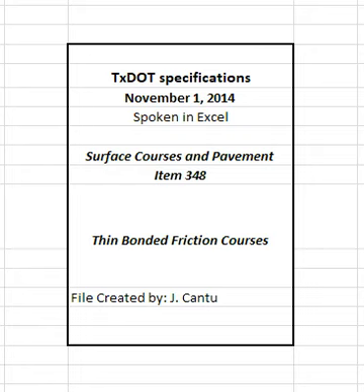4.4.2.1.8 Boil test. Perform the test and retain the tested sample from TEX 530C until completion of the project or as directed. Use this sample for comparison purposes during production. The engineer may waive the requirement for the boil test. Add lime or liquid anti-stripping agent as directed if signs of stripping exist.